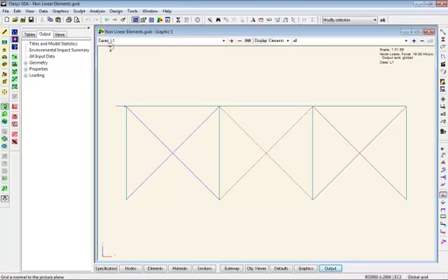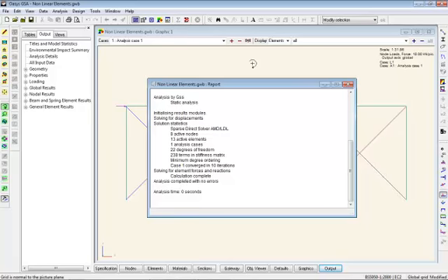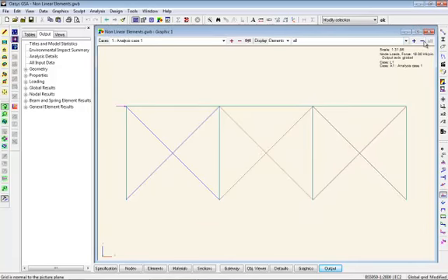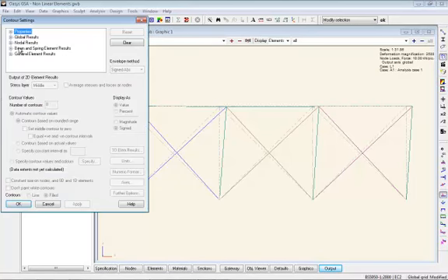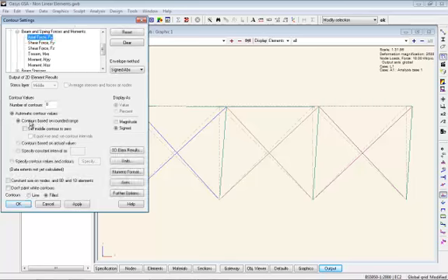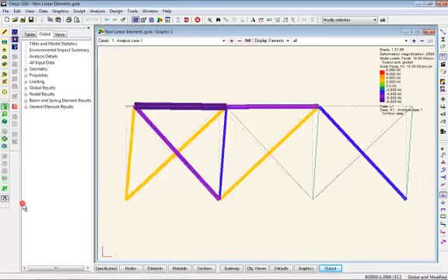Now if we analyse this, and this is non-linear elements, but we're analysing with a linear analysis. The end result is the deformed shape, as you'd expect. But if we look at the axial loads, we can see that with the bars, both are under load, in compression and tension. The ties, only one's under load. With the struts, again, only one is under load.